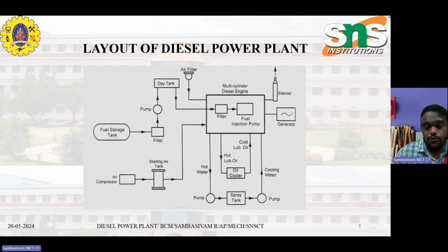This steam is under high pressure and is then passed through a superheater to the turbine. The thermal energy of the steam is converted into mechanical energy through the turbine. The turbine is connected to the same shaft as the alternator. Therefore, the rotation of the turbine also rotates the alternator. This is how mechanical energy is converted into electric energy. Then the energy is transferred for commercial use.